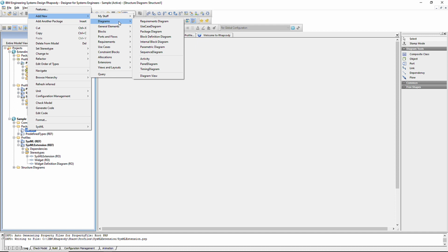Now, if you want to replace the menus entirely, then there are two methods. The first is to define your own custom menus on new term stereotypes. But of course, that requires new term stereotypes, like my package instead of package, which is fine if your profile is a full-blown domain-specific language. But what about menus on regular elements like package? Well, there we can make use of conditional properties.